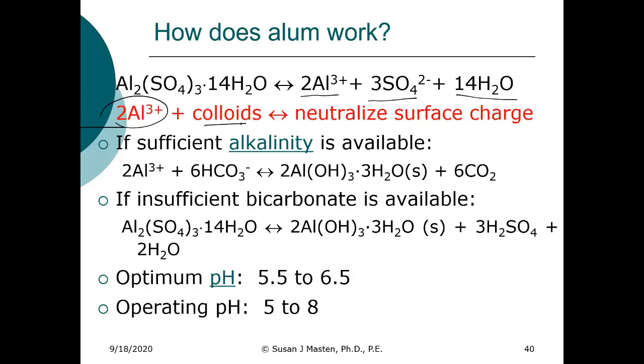If we have sufficient alkalinity present, then these aluminum ions can also react with bicarbonate. And alkalinity in fresh waters is equal to my bicarbonate concentration plus 2 times my carbonate concentration plus my OH minus concentration minus H plus.